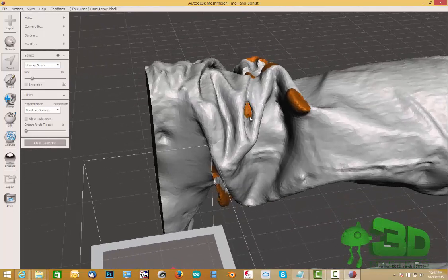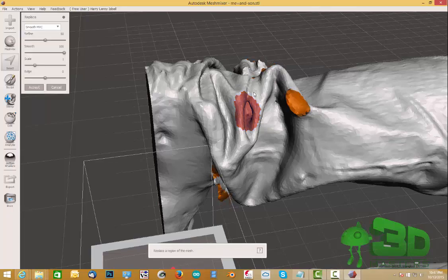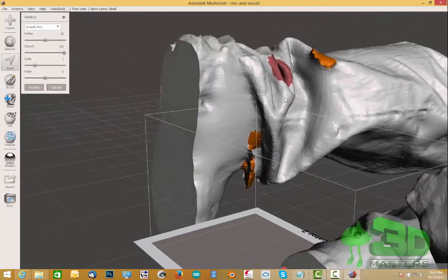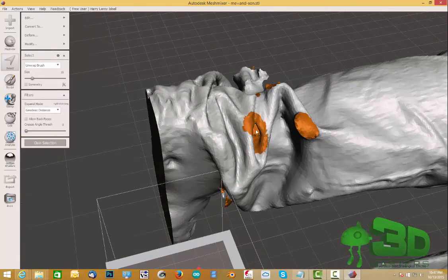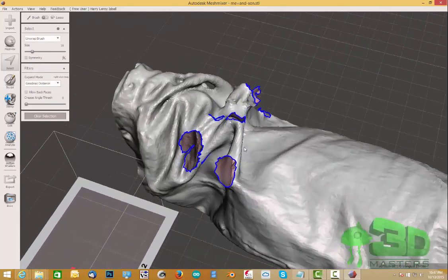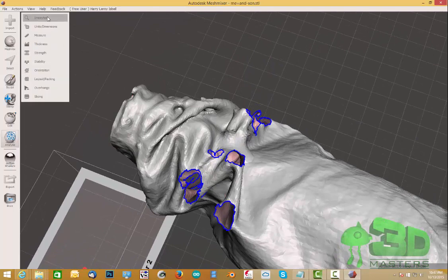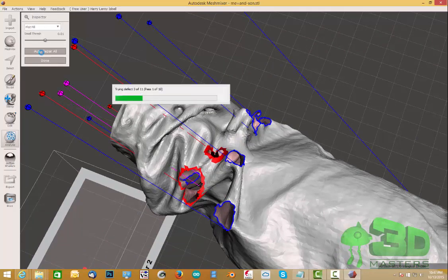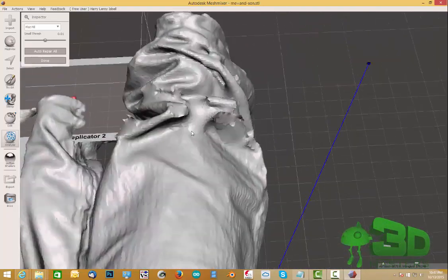And I see a hole right here. So let's kind of get rid of this hole. And I'm going to hit F and try to fix all of them. Okay, notice this one didn't do it because it's too far in. So we're going to have to manually select it. Manually delete this one. Okay. Let's go back to analysis and then inspect and then remove these ones and see if we can repair them. And we did. We did remove them.